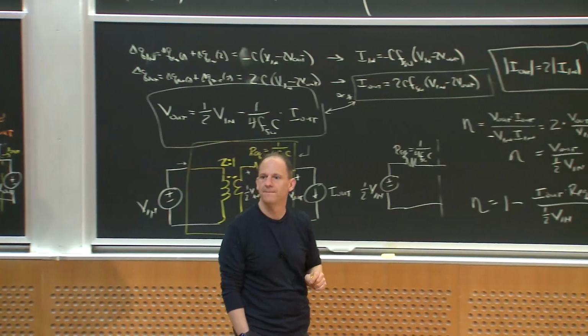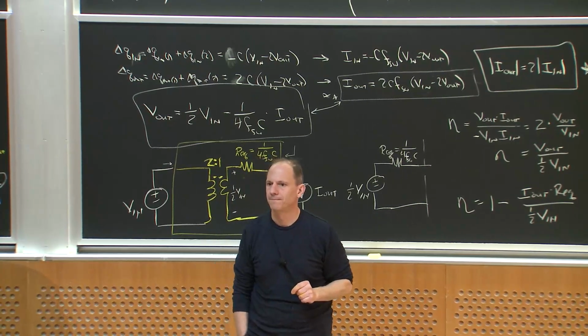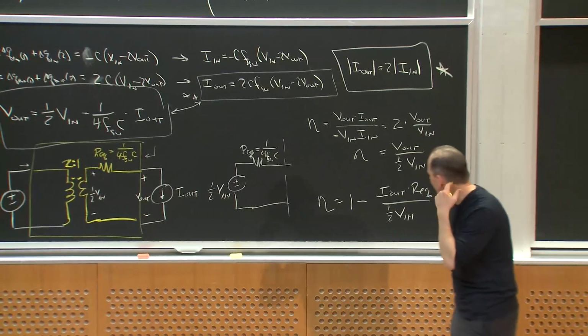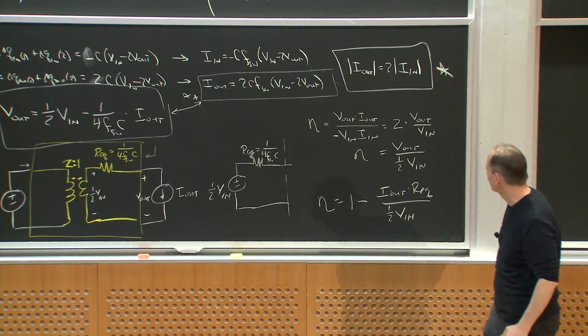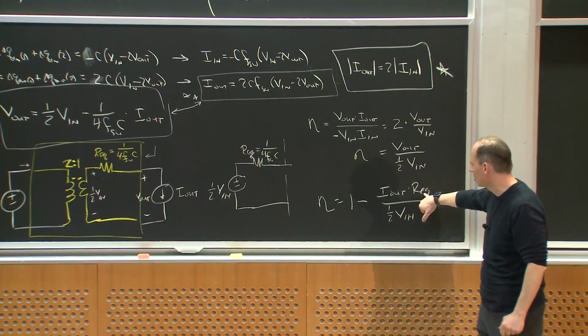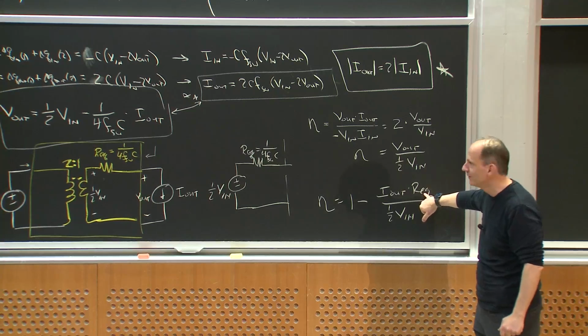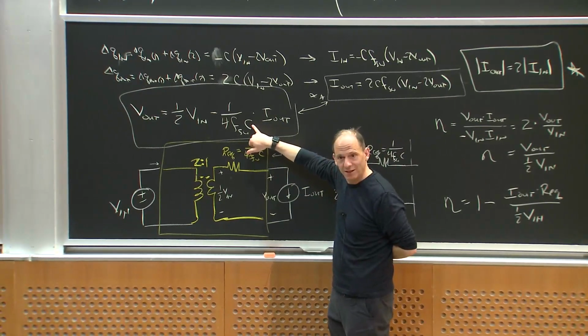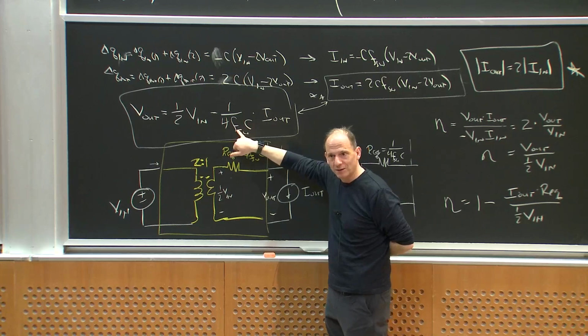Yeah. So if you use a smaller capacitor, which takes less time to charge and discharge, can you see smaller losses? So if I wanted to reduce my losses, let's go back and look at my efficiency characteristic. If I want smaller losses, I should make Req small, right? To make R equivalent small, I should make either C big or switching frequency big.